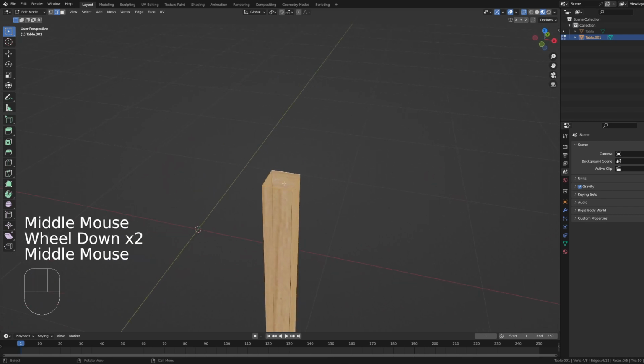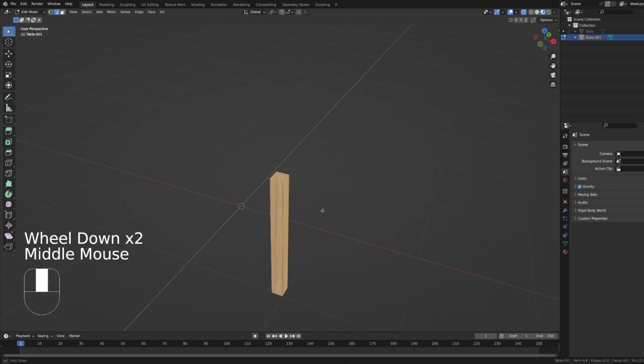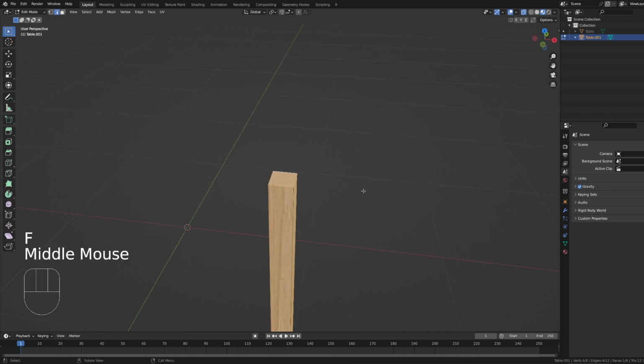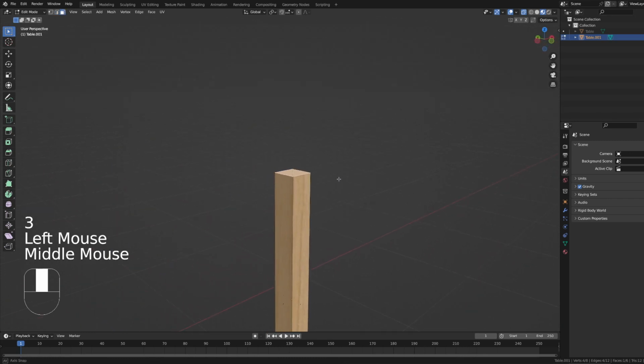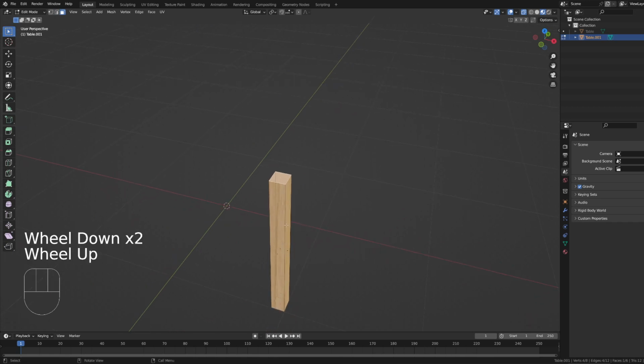First we're going to close this face, so when we animate we don't see through the leg, because this leg is supposed to be a solid object. So after you select the ring, the top edges, press F, that will close off the face. So now you just got this face. Next, we want to move this origin to the top.